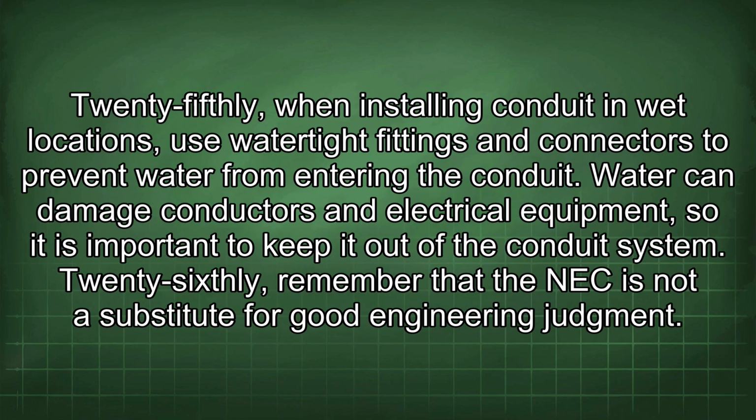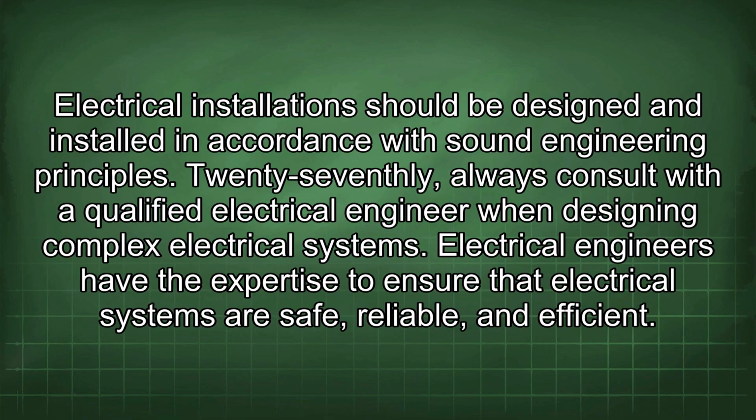25thly, when installing conduit in wet locations, use watertight fittings and connectors to prevent water from entering the conduit. Water can damage conductors and electrical equipment, so it is important to keep it out of the conduit system. 26thly, remember that the NEC is not a substitute for good engineering judgment. Electrical installations should be designed and installed in accordance with sound engineering principles.